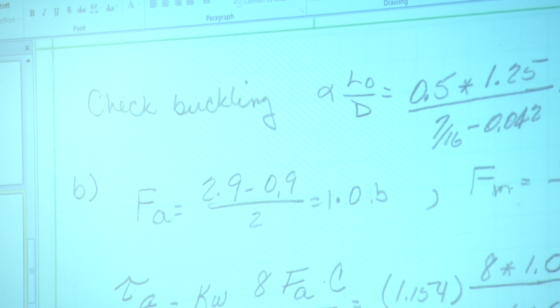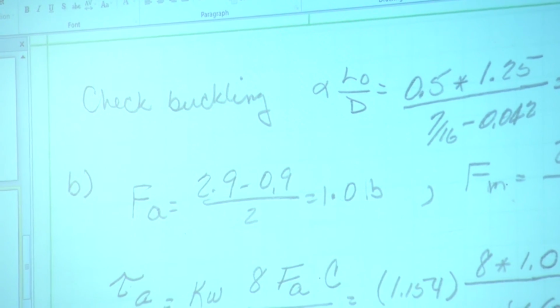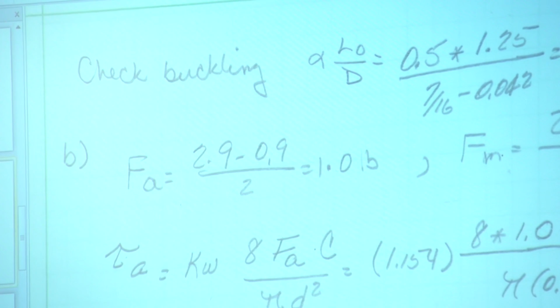In springs that are functioning between two solid parts or flat plates, this is almost always the case. You do not want the force on the spring to go to 0, because if it does, that means it's just loose and it's going to start walking around. In order for it to stay in put, you either have to secure it, however you may, or make sure that the load on it never goes to zero.